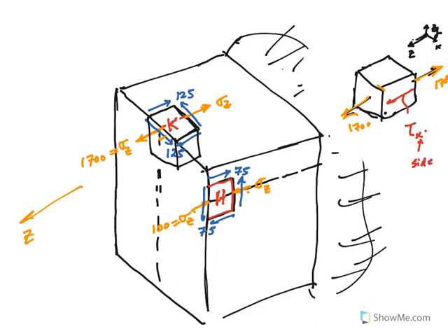And in what direction? Z direction. This is tau xz. This tau would be tau zx. And of course, the same thing will happen on the back face here, and the side face, and one on the back face as shown here. So basically, this is the three-dimensional version of what I have here for you. Okay, and these, I believe, become tau sub zy. Yeah, if you draw a three-dimensional stress element for this guy.